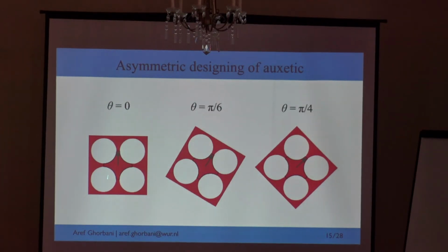It's pretty simple. This is a pretty famous auxetic system, which is designed in metamaterials. This is what they call a supercell. So you repeat this and you have your 2D system. And here, the small thing in the contour is a unit cell, which is oriented in the vertical direction. But we can change this orientation by rotating the grid, and design materials. If we shear in this direction, for example, this one is asymmetric with respect to the direction of the shear. But this one is symmetric, and this one also is symmetric. But let's see how this asymmetry combined with auxeticity affects the result.